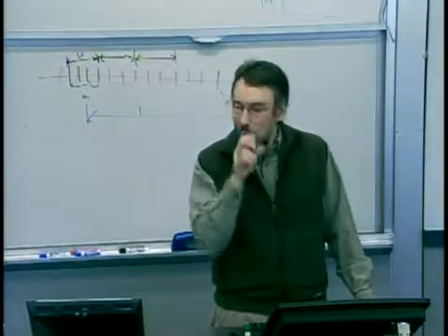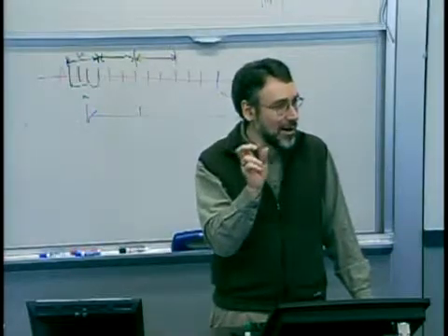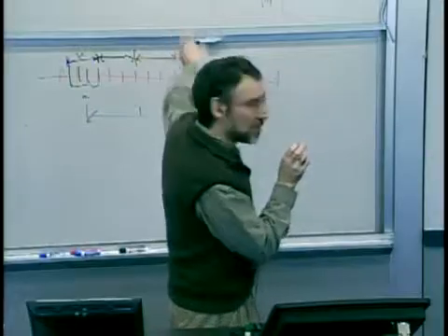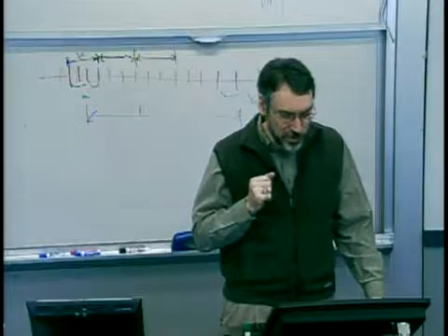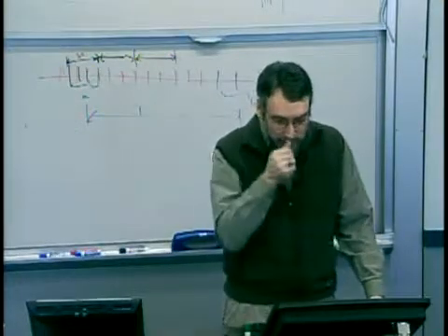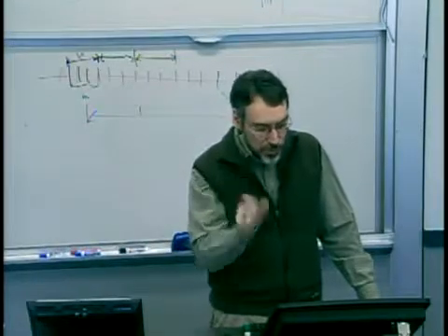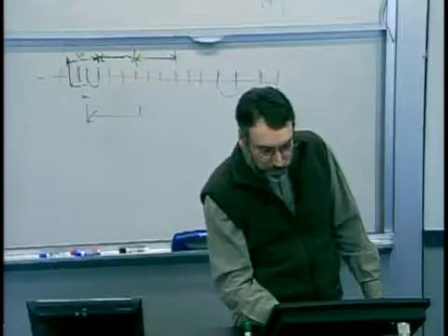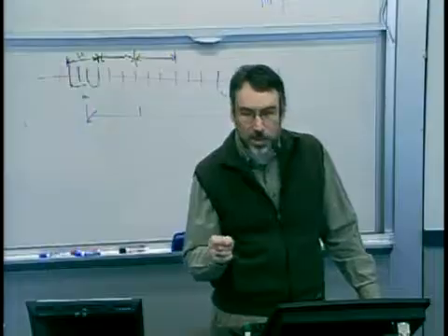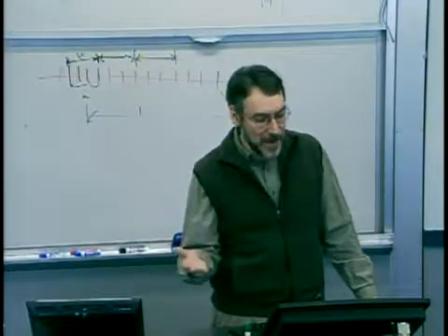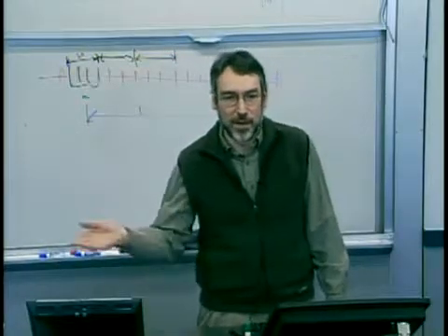Okay, so recall we said back with control charting, detecting small mean shifts of 1 or 2 sigma is actually kind of hard. You actually have to drive sample size way high to have a very rapid detection. What we'd like to do in this case now, I've got still the same inherent variability, or a Cp of 2, but that 2 sigma shift still leaves me 4 sigma before my tail starts impinging very much on my spec limit. And so now I'm here at about 31 or 32 parts per million non-conforming.